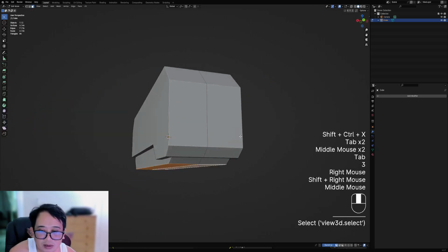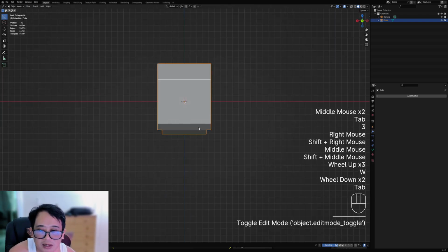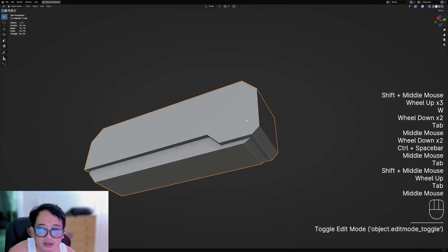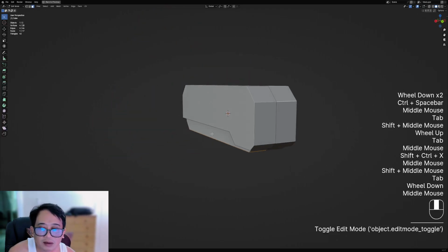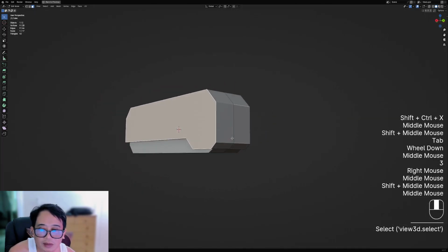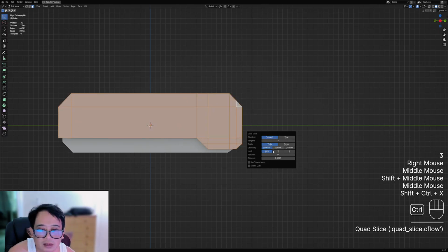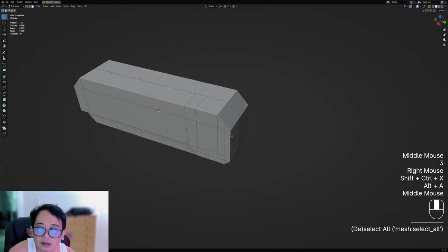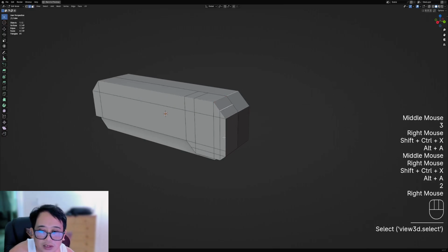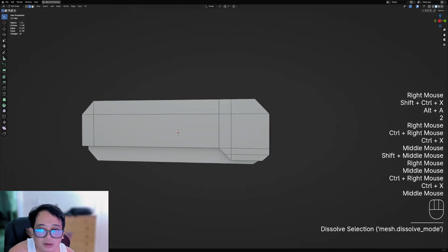And then we're going to scale this to 0 as well, or flatten using loop tools. Flatten. Okay. Now these are straight, and replace the mirror again. Okay. Now we're going to quantify this, selecting the direction using the tangent property. 0.01. Actually, I can remove this and this as well. We have quads here.